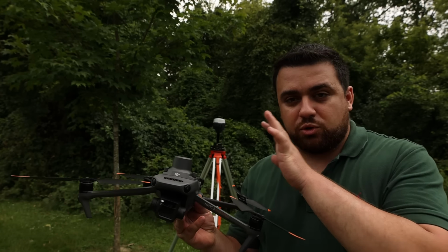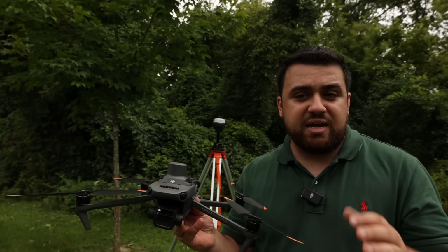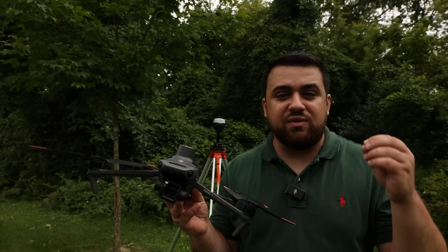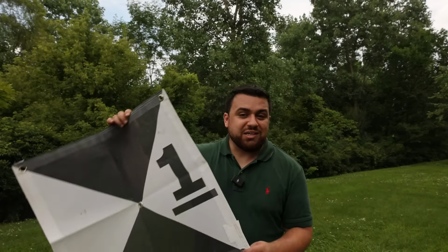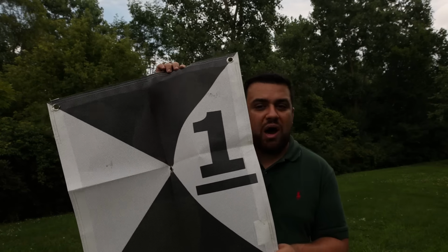So now that you have your drone picked out and you understand how GNSS receivers work, giving us centimeter level accuracy, the next thing we're going to cover is ground control points. Ground control points, or GCPs, are used to aid us in increasing the accuracy of our drone surveys. By using targets like this one with high contrasting colors, we're going to be able to measure on the ground different positions that will give us coordinates for ground control points that we can georeference to our data.